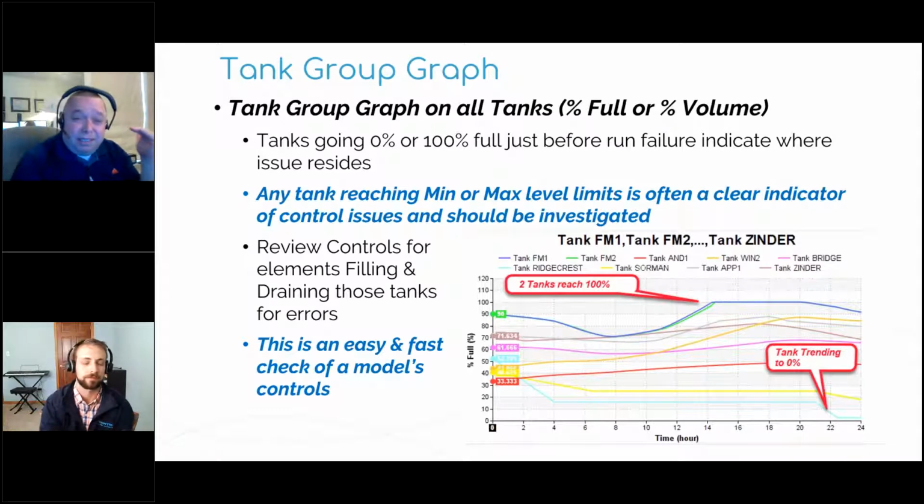Lastly, a lot of those instability issues, if you didn't get any output, are the same problems you can use in troubleshooting. Something may happen and it changes the system operation, so all of a sudden now it's getting to max trials. That's the other kind of issue, and in that case, look through and ask, what does it tell me? Getting a lot of status switching, in that time that it's not converging. Okay, those IDs help me say that's the problem, and let me look at those controls. What's causing that to switch so much?